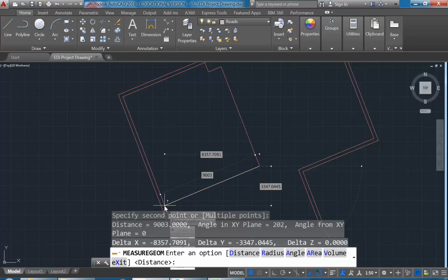And when you go to put in even things like, say, ceiling panels, they need to fit exactly. And so you need to be able to give those sizes exactly to the builders. So when you do your own projects, if you're going to have things built from your measurements, then it's important that you can take accurate measurements. And if something's not square, don't draw it as square. But in this case, we can cheat a little bit and round off those measurements.